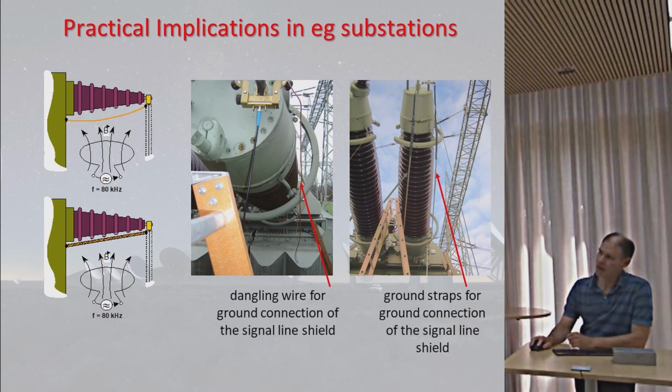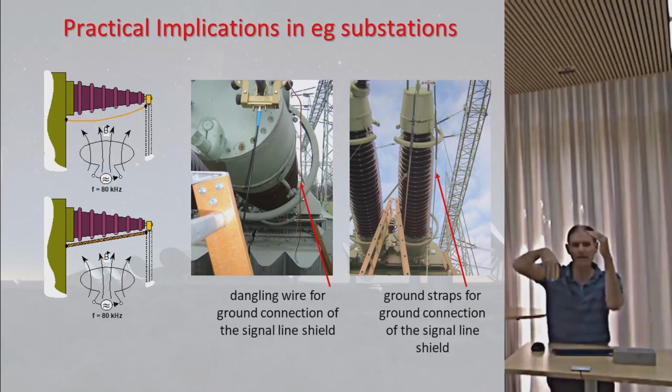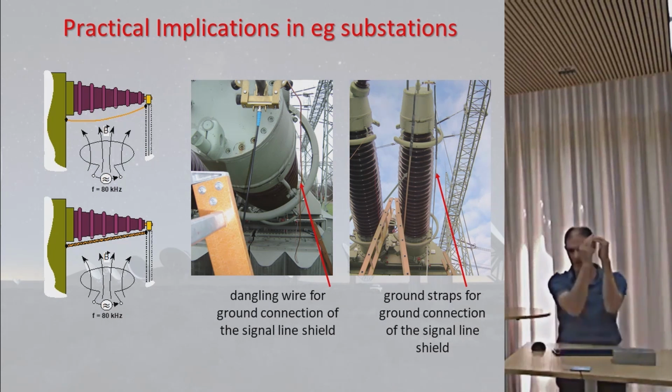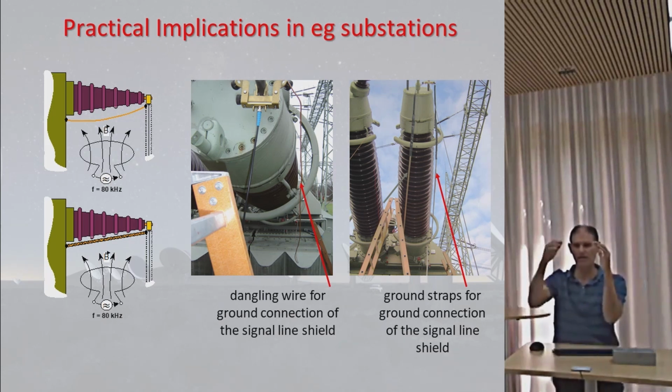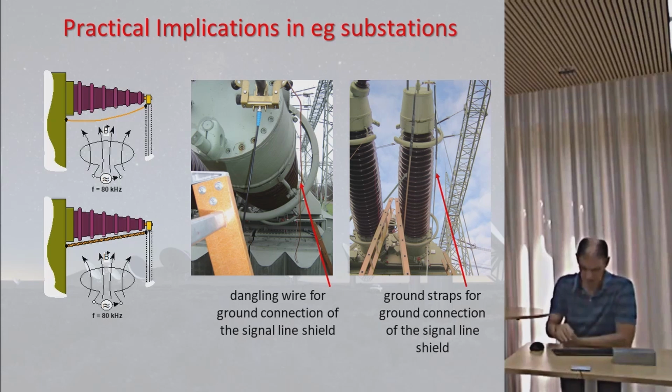In the dangling wire experiment here in the middle, you will find that you've got a measurement circuit with a coaxial cable. You've got a dangling earth reference. You've got a central bushing, and that forms a 3-wire experiment. Because the dangling wire is undefined, the coupling in that experiment or interference is quite bad. But if you define the loop using a very well-positioned earth strap, what you find is the coupling gets reduced, and it's always the same. It doesn't depend on what the measurement wire does, because I've now defined the first loop. And this becomes important for making very, very sensitive measurements.